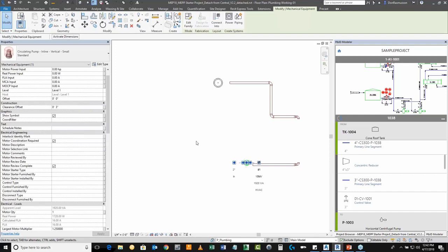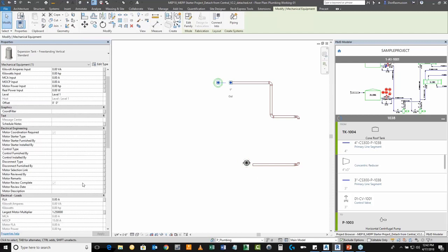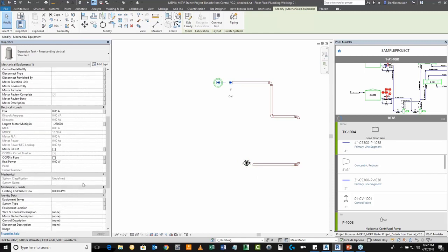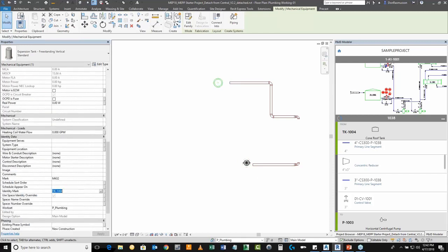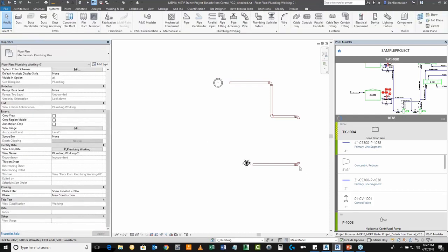But also at times when there is a discrepancy between what it understands as information from PNID and what it understands as information from Revit, and they don't match, you will get a different color in that green area. I'm going to see if I can force it here by doing that. And yes, I can. So here you see that you have green and yellow as a cautionary tale. As I hover over that, the Revit part does not match.